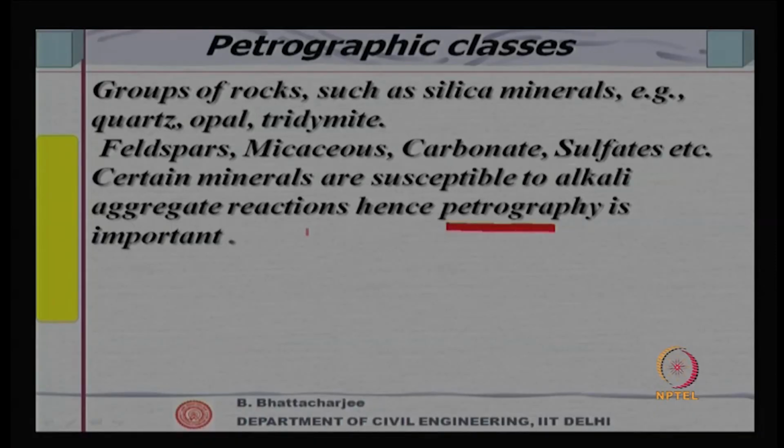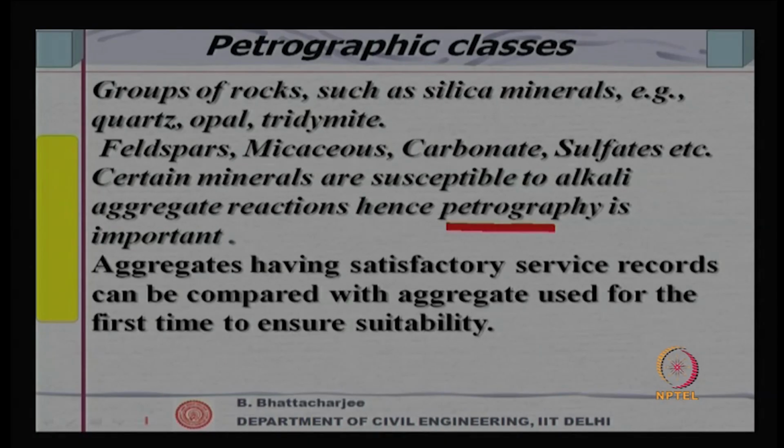We will look into this issue of alkali aggregate reaction in detail when we talk of durability of concrete. So, certain aggregates are prone to such durability problem and cause deterioration of concrete structure. So, petrographic analysis is very important, because you can then identify the mineralogical compositions, and the minerals, if present in the aggregate, can make the concrete susceptible to alkali aggregate reaction.